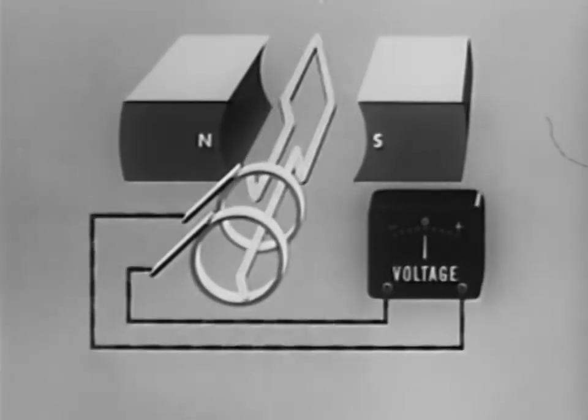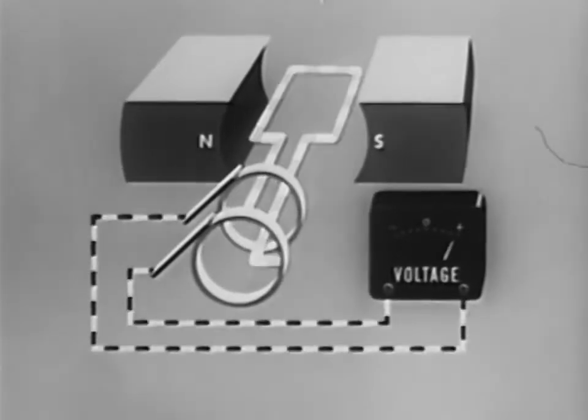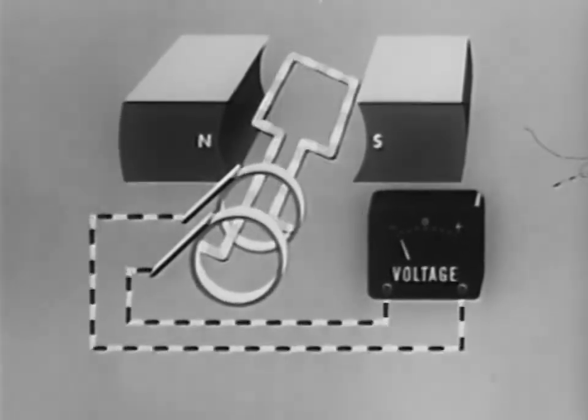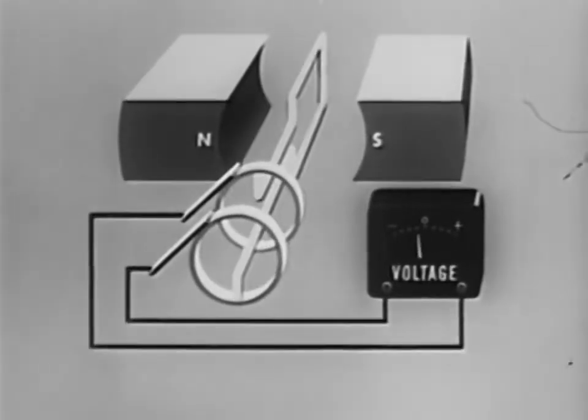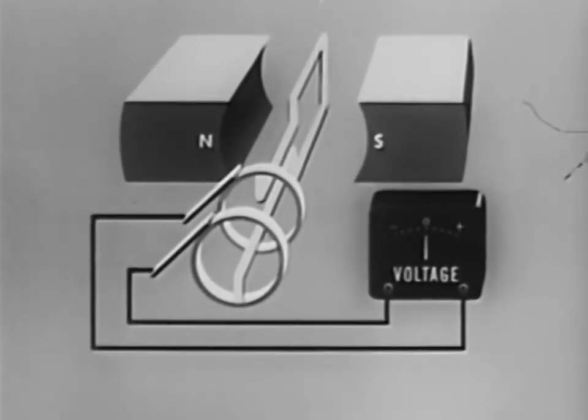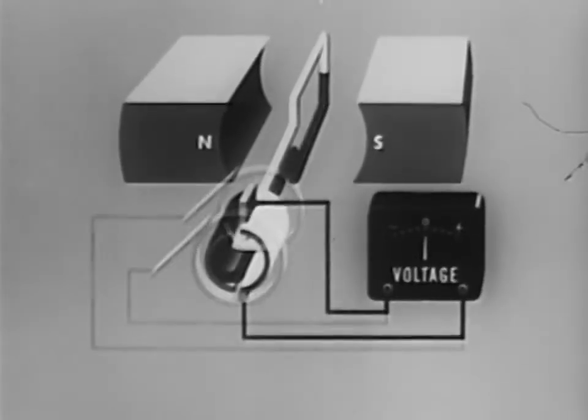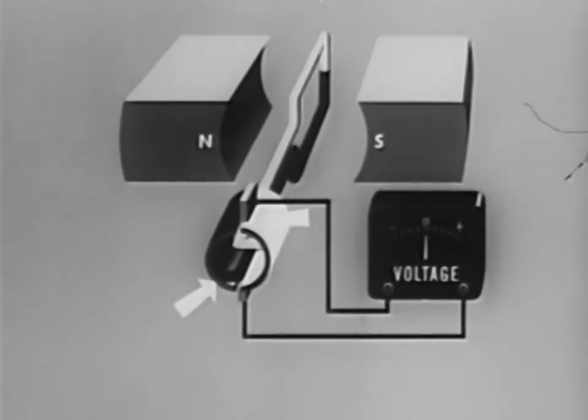What you have seen so far is really the theory and operation of a basic AC generator, but our purpose was to explain the principles of operation of a DC generator. To get direct current, we will attach each end of the conductor to a segment of copper, forming a commutator. Now our machine is a DC generator.